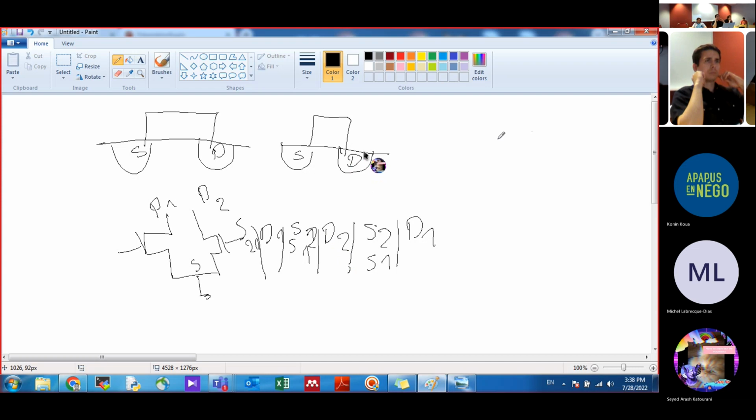But okay, what I wanted to say is that usually for diff pair and for current source, the matching is very important. So what we used to do is make a centered approach for that. Let's say if you call this one the device A and this one the device B, for example, you can have a pattern.